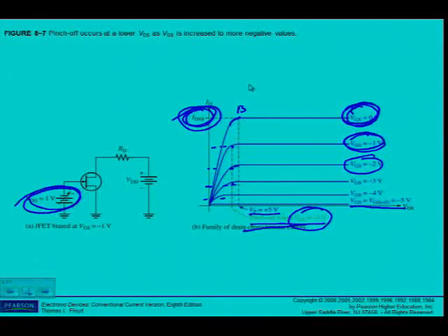It will be a bit clearer in a picture that we get to later, but if I can refer back to 8.7, that perhaps you have noticed by now. On this example, can you see that VGS, which is equal to VGS off, is equal to minus 5 volts. But look at the value of V pinch-off, plus 5 volts. I will show it to you again in a later graph.